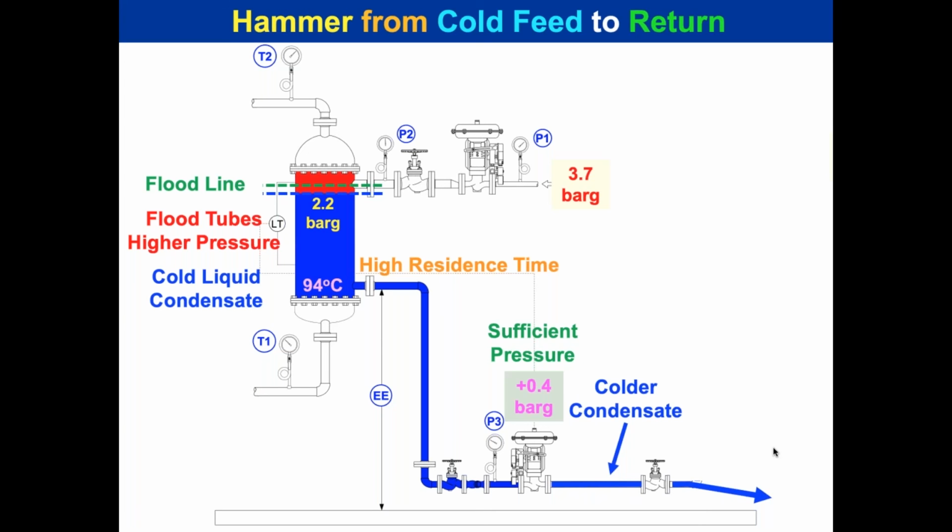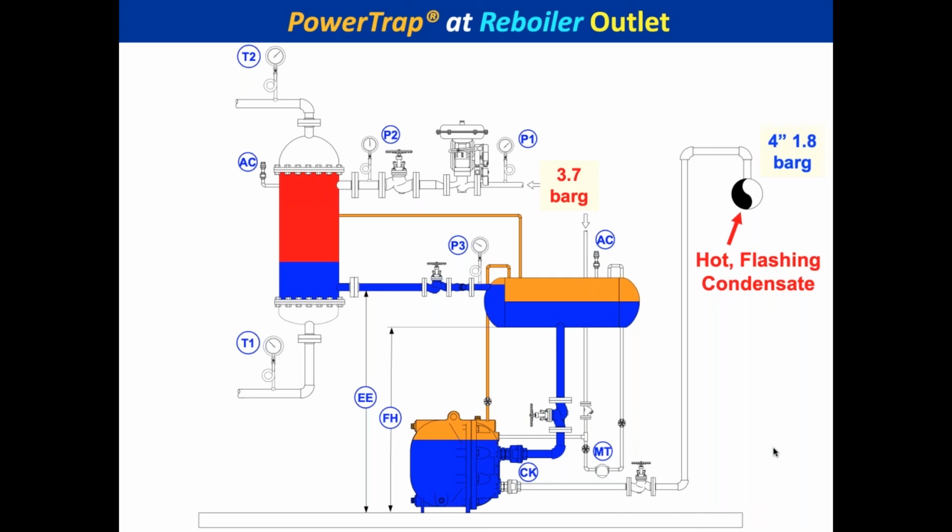So my friend said, what should I do? And I said, well, that's pretty simple. Just put in a power trap, a simple little power trap. You can take the 3.7 bar G to motivate it. Use a little 8-inch pipe for the reservoir. Everything's fine. One of the collaborators today, Justin McFarland, drew that system out for me.